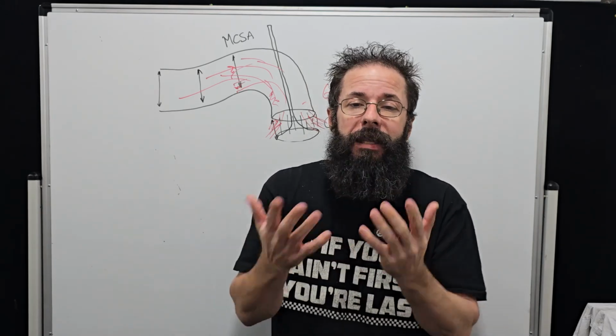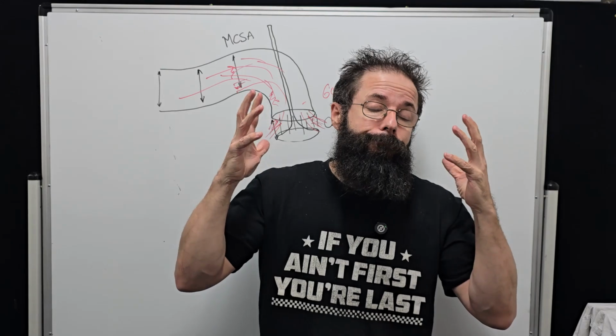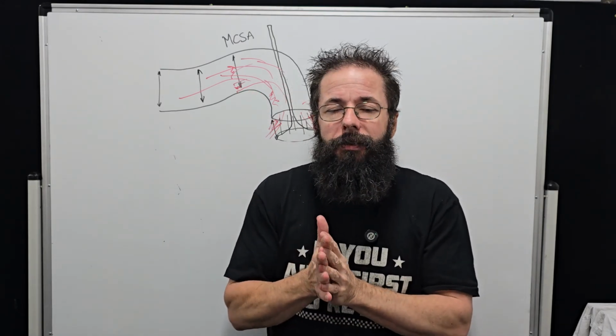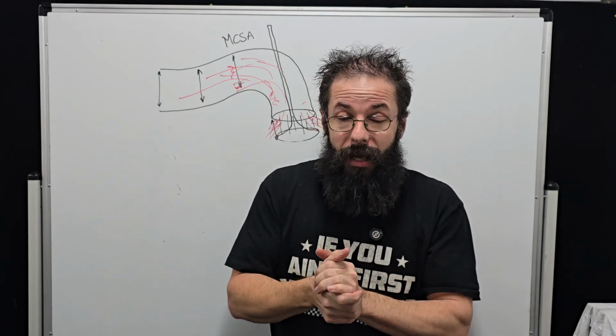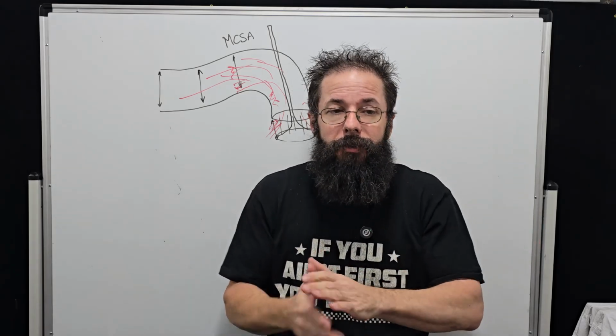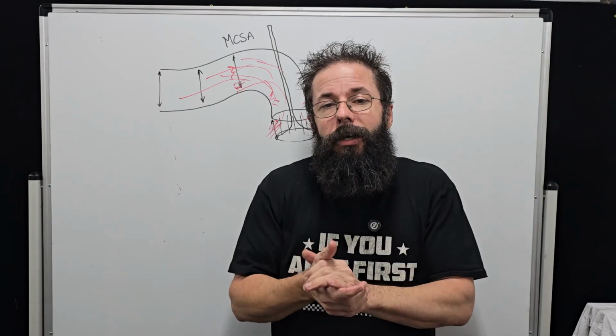Now, the other problem with OEM is some of the areas are much bigger than they need to be because they have bends in them. And again, this comes back to our pressure gradients in the pipes and obviously our flow gradients. Because we have a bend, we're going to reduce that cross-sectional area. So what OEM do to compensate, so they still get their harmonic lengths long enough to create plenty of torque, the diameters are much bigger.